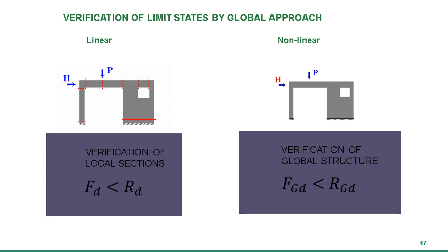And actually, they are used as a kind of model approach to developing the new generation of Eurocodes, which was mentioned previously by Steve. So let's just make first some kind of basic comparison. If you think about how we work today, we typically perform a linear analysis of our structures, and then we check the critical sections and check whether the internal forces in those sections are smaller than the design strength.